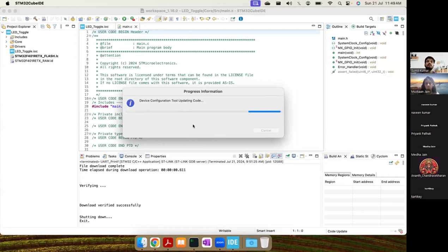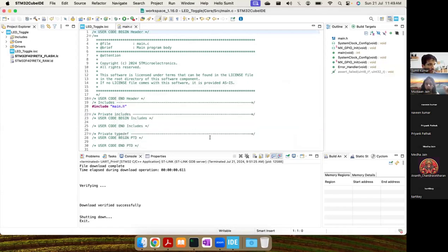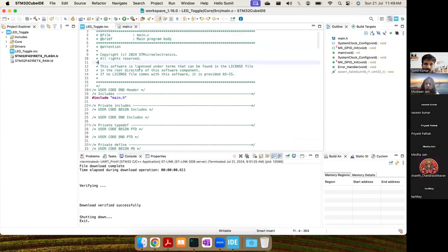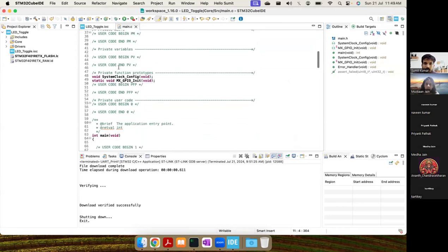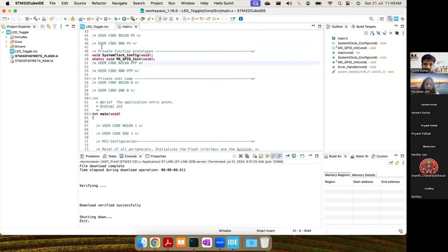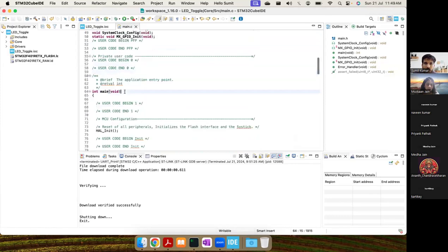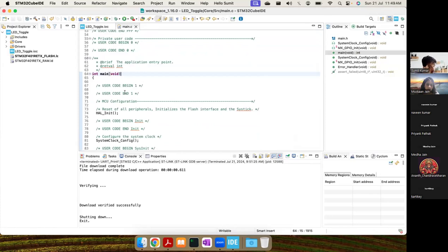So we can also use this MCO2 output, basically the clock of one board, and give that same clock to another board by connecting the MCO2 output to the other board's pin, right? And we can do the same thing, right? Yeah.